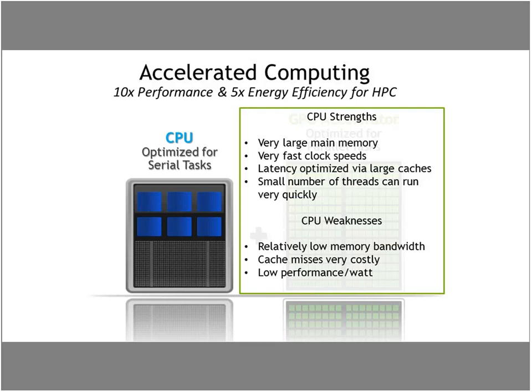But at the end of the day, because the CPU has to put so much space towards caches and so much logic in branch prediction, in cache prefetching, and out-of-order processing in order to keep these cores busy, more of the power goes to that and less of the power goes to computation. And so that means it has a relatively low performance per watt.